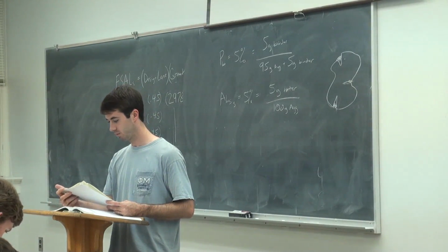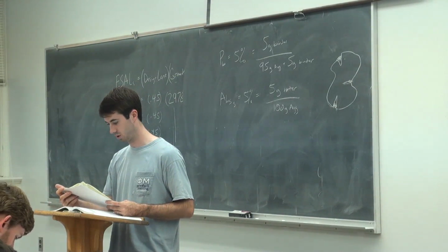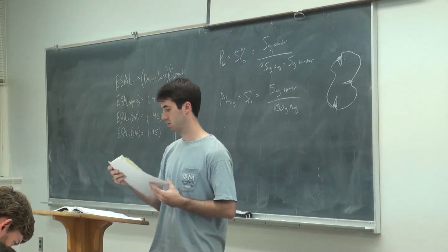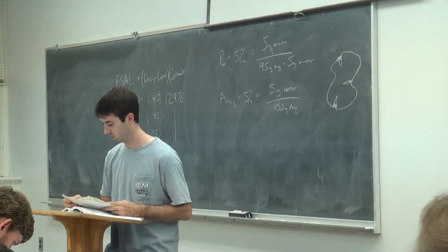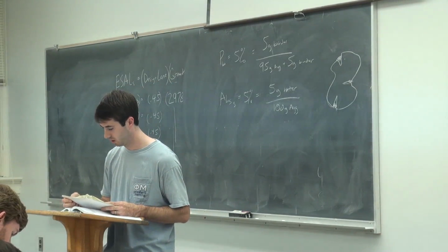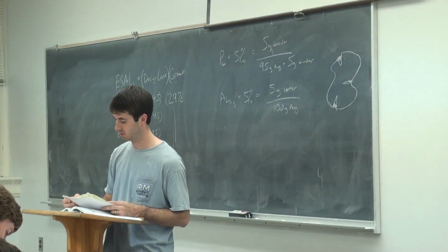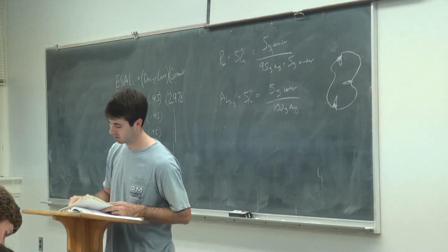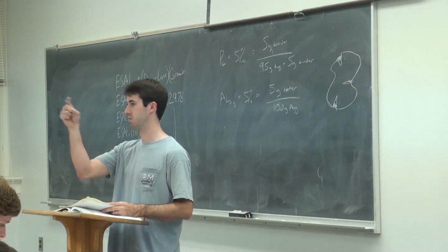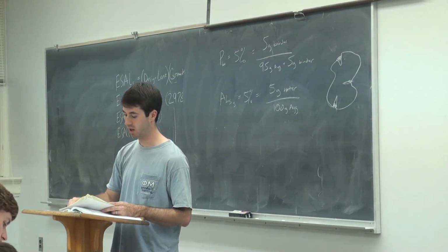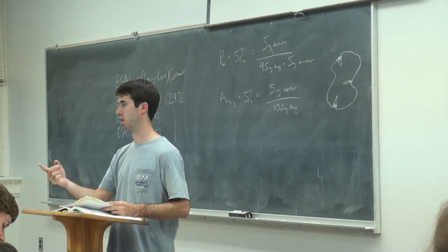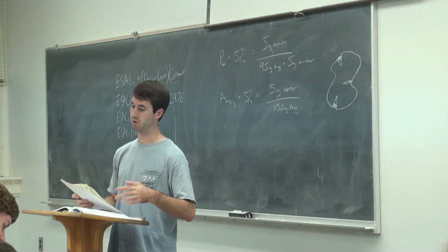All right. Let's see. Just kind of running through it. Some things to note. That top right table, mixture designations. You've got the nominal max size. So the Superpave says a 9.5 millimeter mix. That means nominal max of 9.5. Maximum size, first sieve size bumps up after that. So for 9.5, the next one up is 12.5. For 19, the next one up is 25. It always falls in that order.